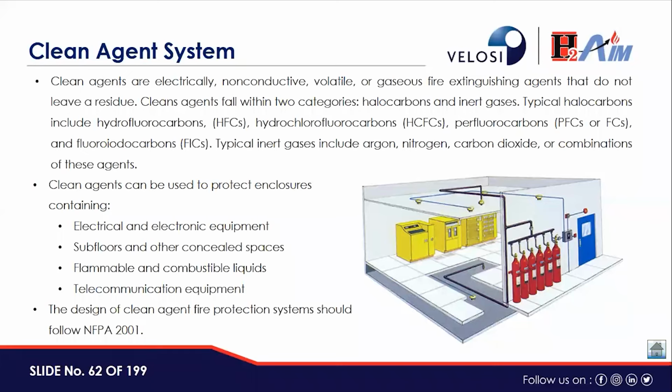Then clean agent system. These clean agents are electrically non-conductive, volatile, or gaseous fire extinguishing agents that do not leave a residue. Clean agents fall within two categories. First is halocarbons and inert gases.